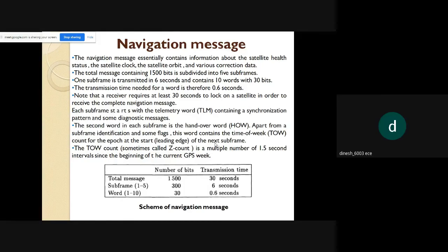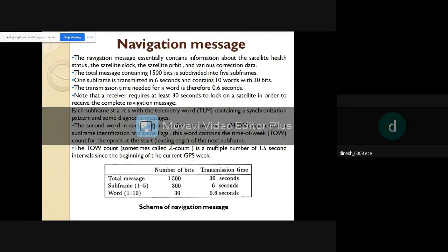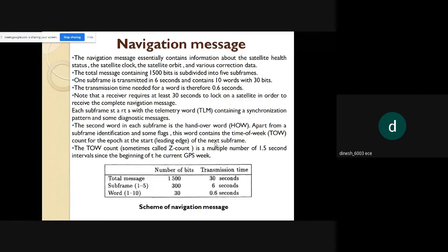So each and every subframe will be transmitted every 6 seconds, having 10 words with 30 bits. And the transmission time needed for a word would therefore be, since it is 10 words in 6 seconds, for every word we require only 0.6 seconds for transmission.